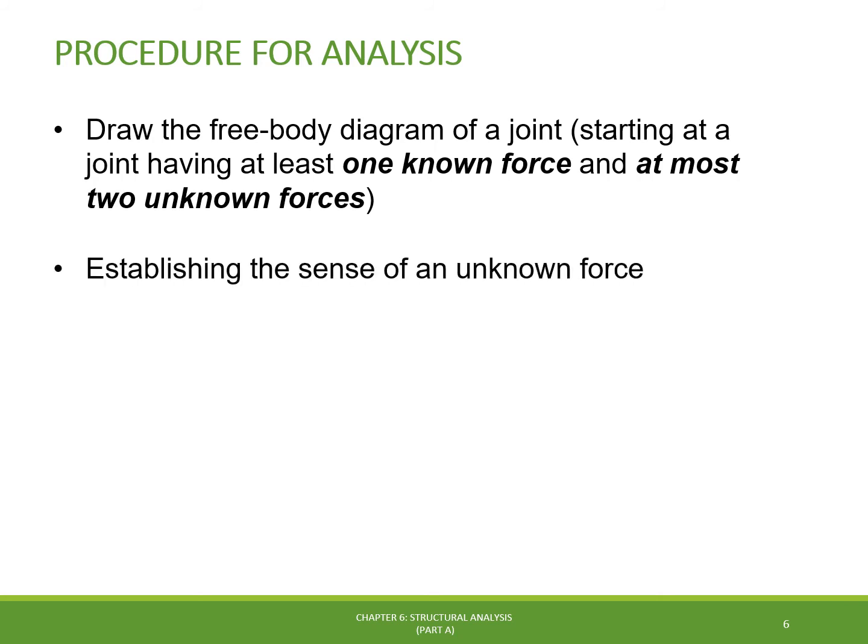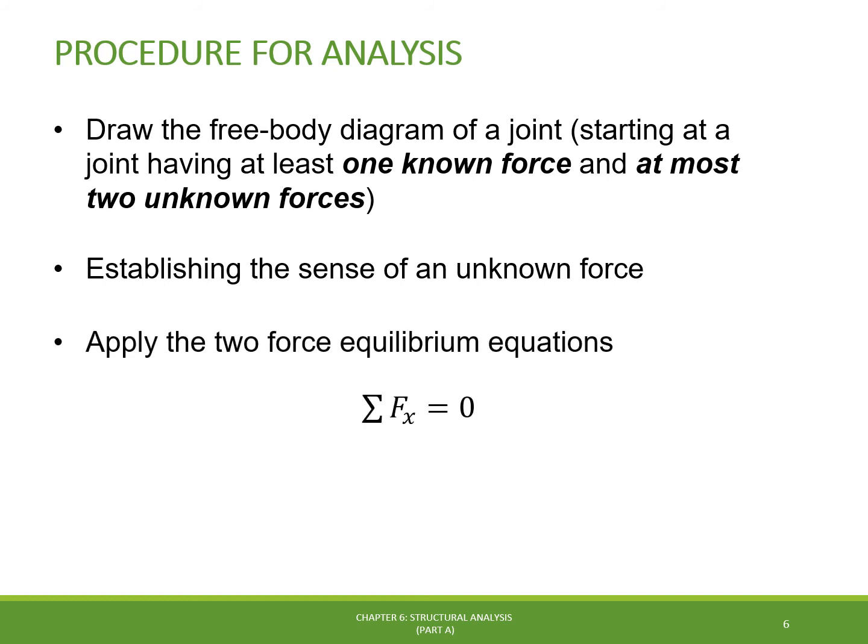Next, we have to establish the sense of the unknown forces by inspecting the free body diagram as explained in the previous slide, or just assuming it and checking after the calculations are done. Then, based on the orientation of the x and y coordinate axes selected in the free body diagram, we have to resolve all forces into their x and y components, apply the 2 force equilibrium equations, solve for the 2 unknown members' forces, and verify their correct sense.